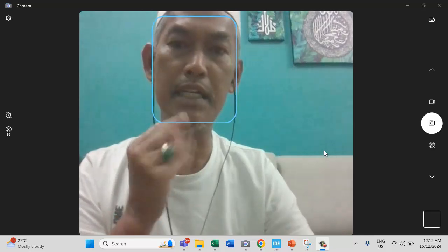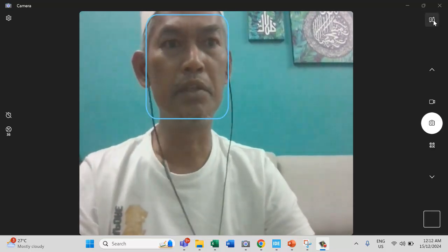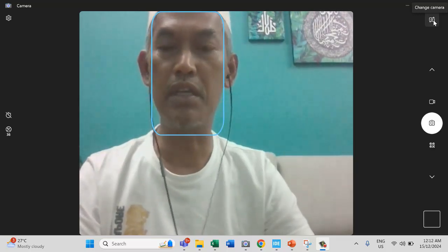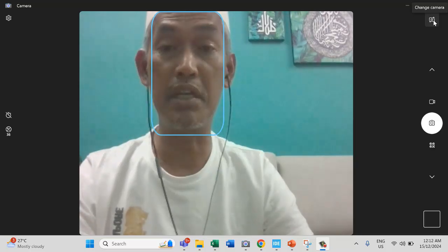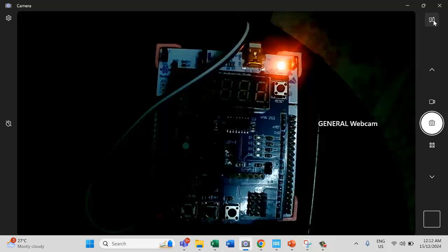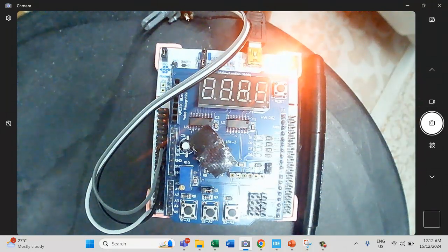Today in this video, I will show you how to program the analog channel in multi-channel analog. Please connect another variable resistor. Remember to connect it to 3.3 volt and ground for the voltage, and for the wiper, connect it to the last pin here, PC3, I think.